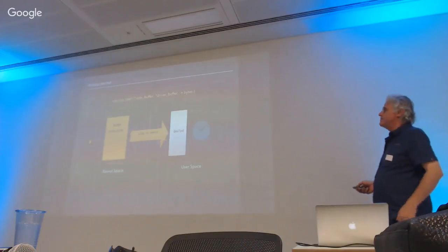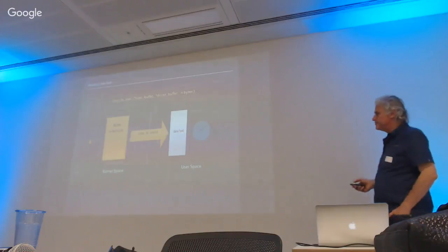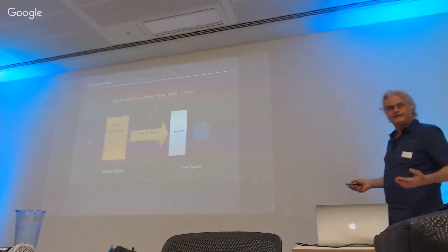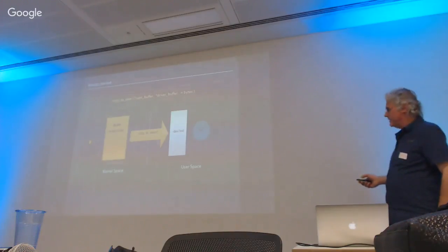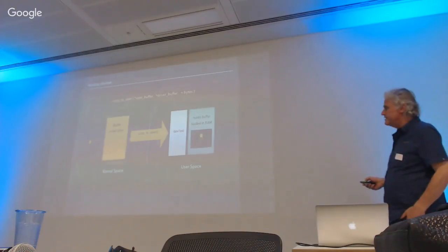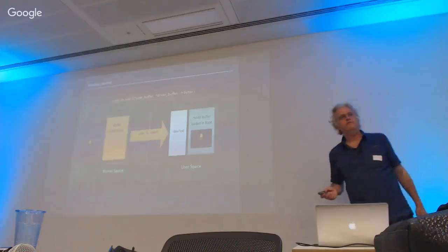And likewise, when we want to send data from the driver to an application in user space, it's got something to send, copy_to_user in this case. Again, it will wait until a buffer becomes available, and then we can send the status of this LED into the buffer that's available in RAM, and then the application can do something with it.